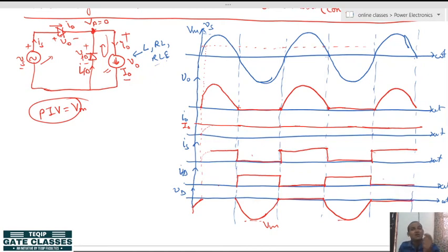So if you consider an infinite number of cycles, this one half cycle is just a trivial one. You can neglect it, because it will never appear again. That's why in books, whenever you see a continuous current load with a freewheeling diode, they make the output voltage and the source current like this. They don't show the E effect, and the diode voltage I made here will never appear again. So in books they show the complete waveforms like this.